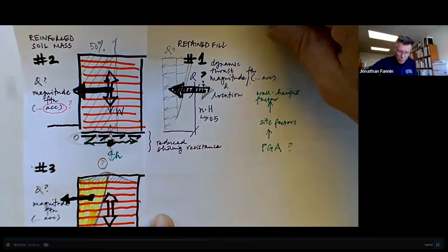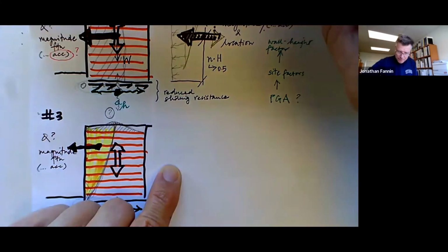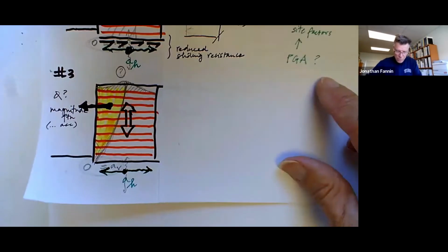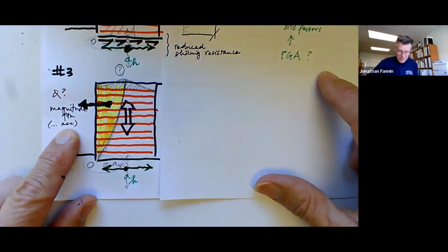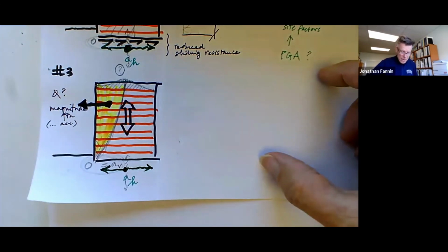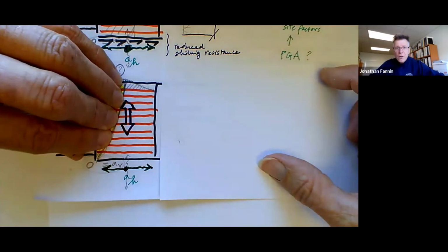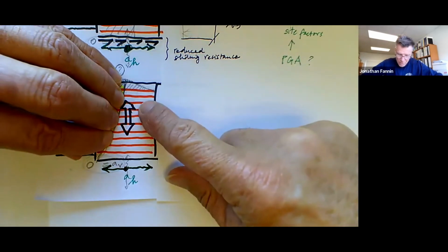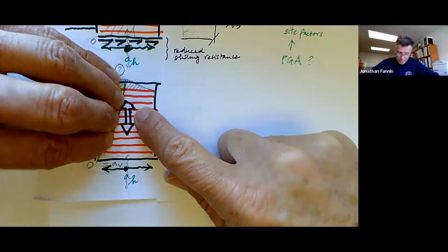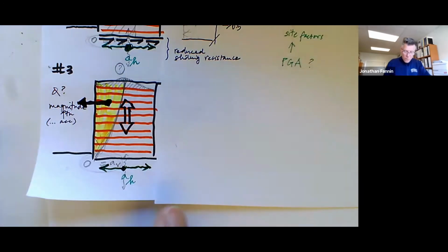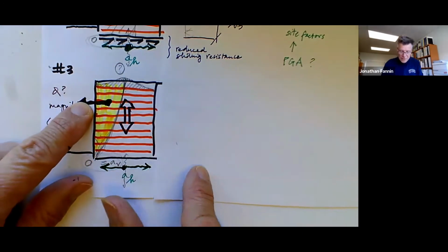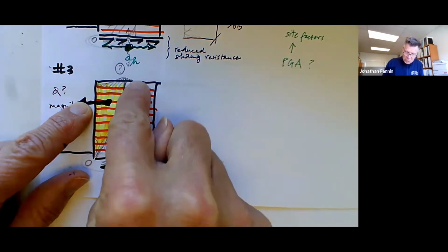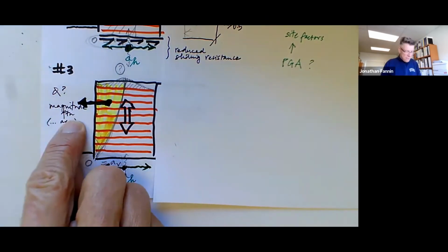And moving to the internal stability, having addressed and determined what this acceleration is, now we have this zone placing an incremental demand of tension. So we find out what the magnitude of this thrust is, and now we have to say, wow, each of these layers takes some proportion of this thrust.